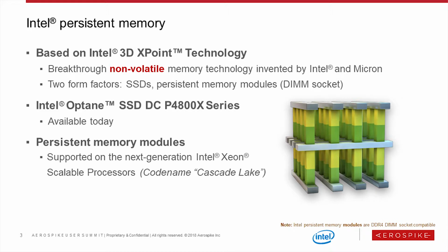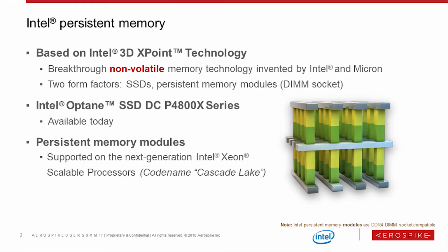But at a high level, what you see there are columns of memory cells. There's a memory cell itself and then a selector. The bars on the top and in between and the bottom are wires that connect the memory cells. So for instance, what you would do in order to select a memory cell would be to maybe take the top leftmost wire, select that one, select the wire that's in the front, and the intersection of that is just one single memory cell. So this is in stark contrast to maybe a traditional memory technology where you're selecting an entire row.